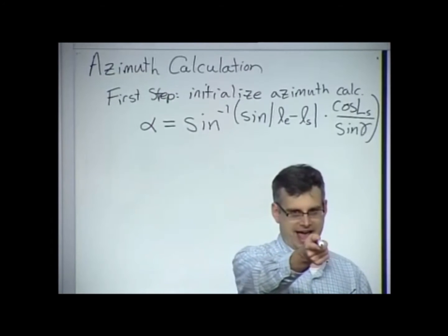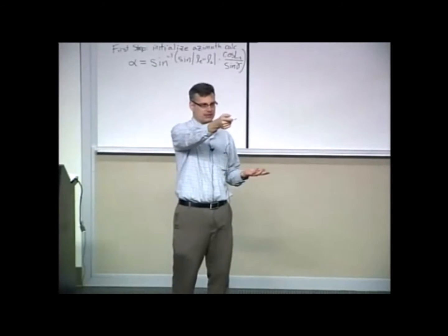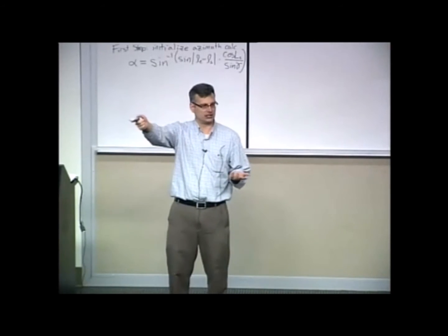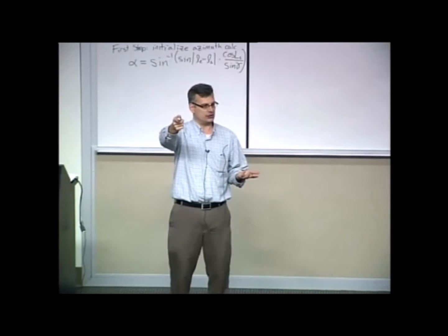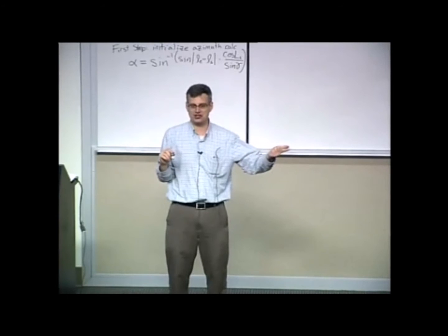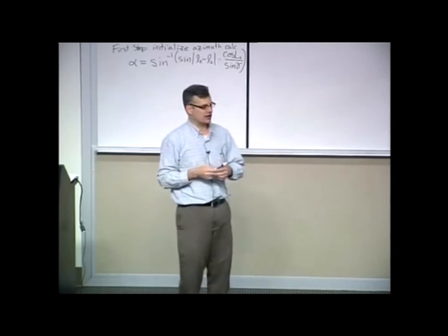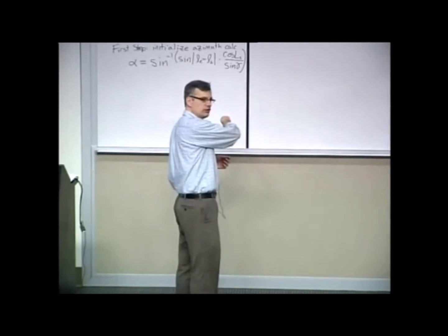We're measuring the angle that you steer something along the horizon perpendicular to elevation in order to sight in your antenna. Where do we measure it from? Well, again, here's a case where we differ from mathematicians and engineers. We use the cartographer's convention for azimuth. And that's where north is 0 degrees and east is 90 degrees.